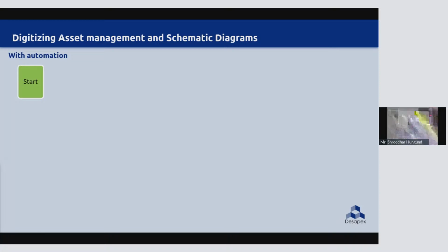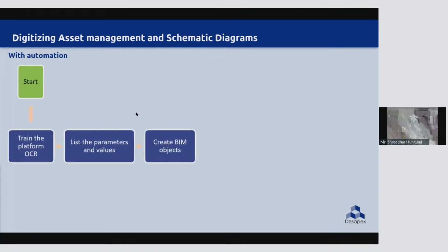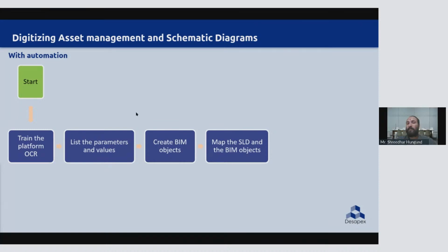Desapex proposed to develop a digital single line diagram that has objects in 2D representation of the schematics, but still contains the metadata related to technical specifications. We used BIM authoring software, BIM automation tools, and RPA platform to address this. But still, the major challenge was to feed all technical information and equipment ID of these motors, panels, circuit breakers, transformers, etc., all into the system.